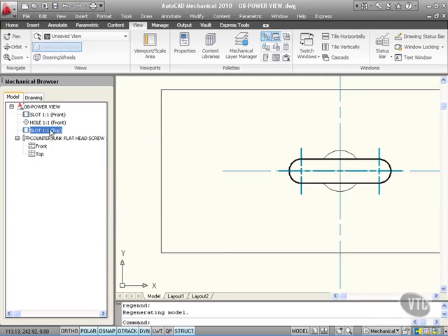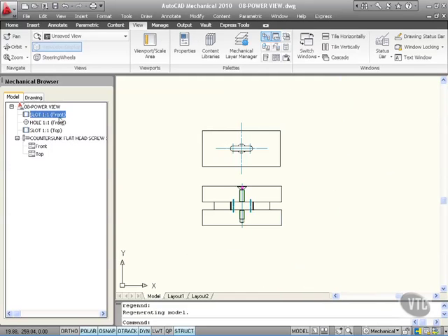But you can see there that I have a slot with a top view. I also have the front view there. If I just zoom out a bit there, there's the front view, and there's the top view, like before. There's the countersunk flathead screw there, and there's front and top. So those Power Views there are extremely useful. But as you can see, you can place them on top of each other the wrong way. So you do need to look at how you hide things and how you place things on top of each other in your AutoCAD Mechanical drawing.